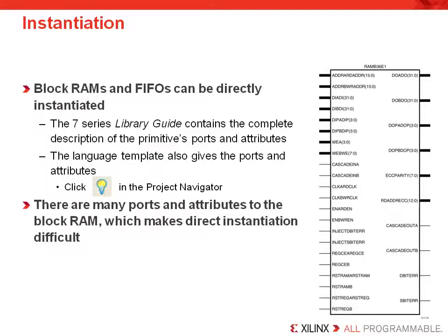But if you do want to instantiate a component from the Xilinx Unified Library, you can simply go to the Language Template Utility, which is part of the ISE software, and you can find the component listed there and then simply instantiate it as you would like.